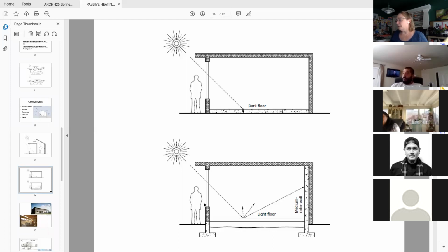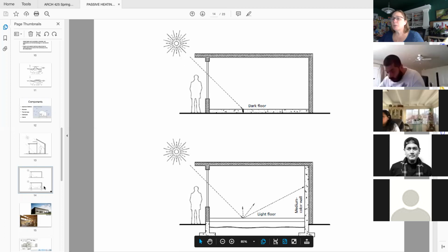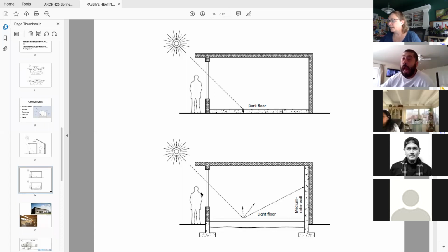So you have to find that sweet spot, the balance between good performance for your mechanical system, but if you are relying on your passive system, you also want to let your solar heat gain in. So you've got to split that difference somewhere. But just keep in mind, the key part is no low-E coatings on the glazing or the absorber in a passive heating system.